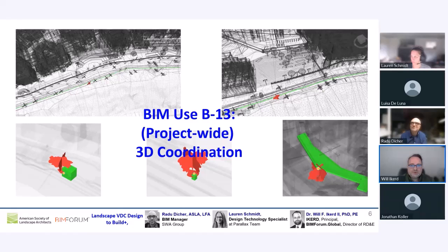And so once you start doing just a little unit change, international feet to US survey feet, you can create large discrepancies. And it's not the software's problem. This stuff's known by some, and it's going to be communication, I think.